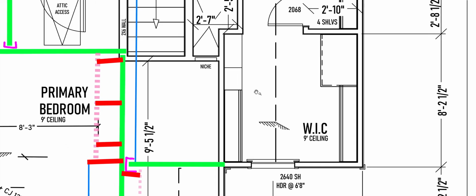Now, I happen to know that if I start at this wall for bracing, I can go at a 45-degree angle up with a brace, and I'm good with that. So I need to figure out approximately where that purlin is going to meet this roof slope. So this roof is sloping up at a 10-12.